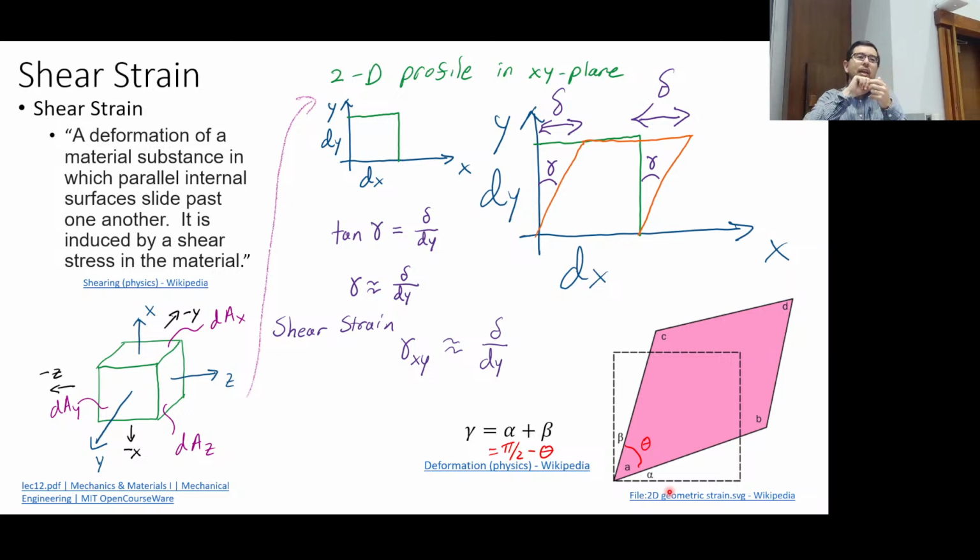So yes, if I have a very strong material embedded inside of another material, and all the strong material is going in one direction, then it makes sense that the structure is going to be much stiffer. The elastic modulus of the material itself is going to be higher in the direction that the fibers are going. And if I want to pull in the orthogonal direction, it's going to be a little bit less in its elastic modulus in that direction. So that's a very good example of an anisotropic material.